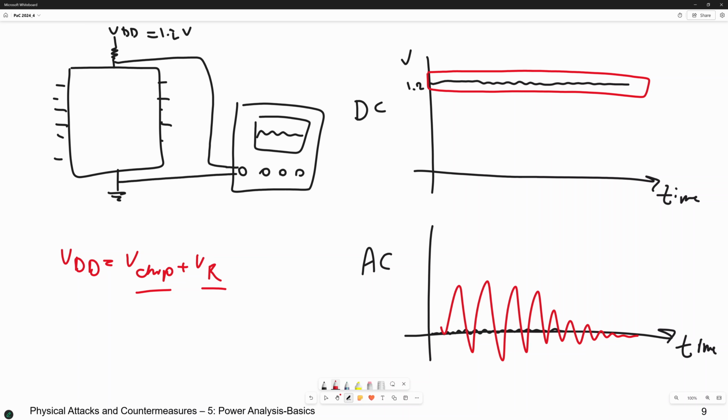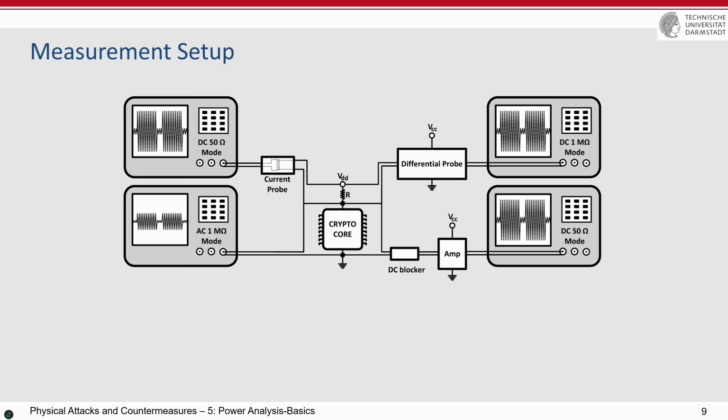Good. That was the current probe and all of them together in one picture. But you see, you have to change the PCB. PCB is clear, printed circuit board. And then you have to find this VDD, and it's not always easy because the chip usually doesn't have a single VDD line. There are multiple VDD lines that are connected internally inside the circuit, but there are multiple pins, and you should provide the VDD to all pins.